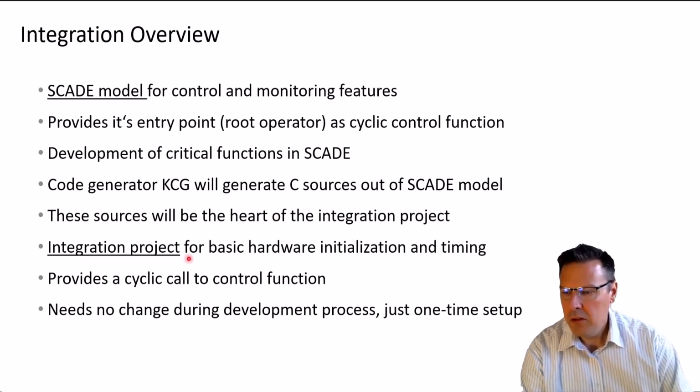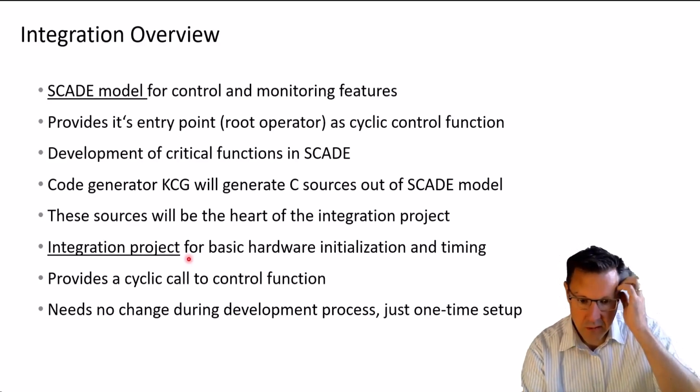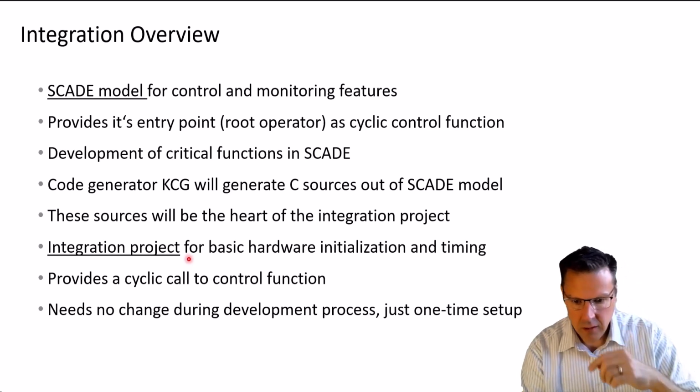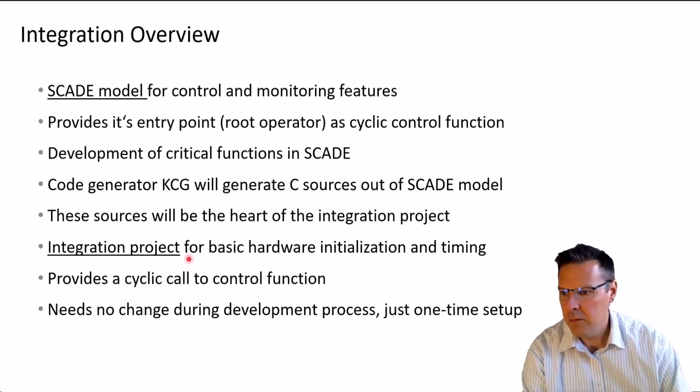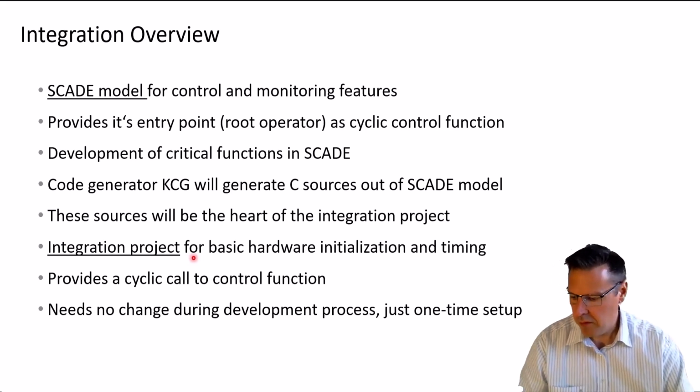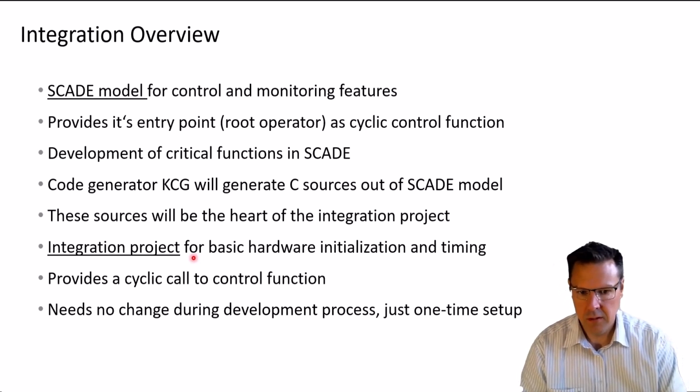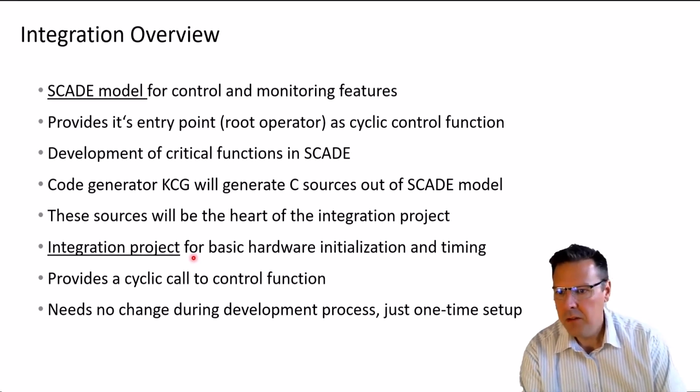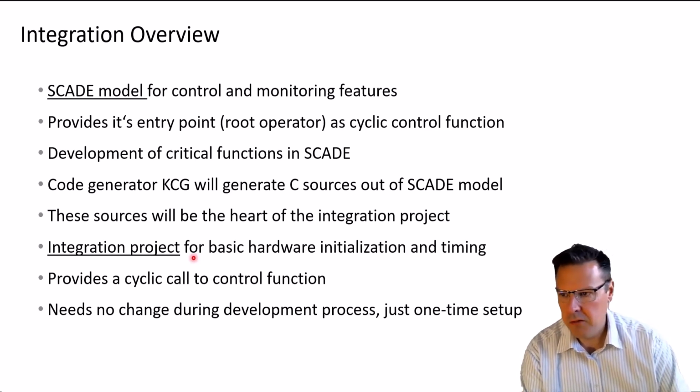Why do we need this integration project? SCADE is quite well abstracted from any hardware aspects. So for basic hardware initializations, hardware interrupt handling, basic port initializations, things like that, all the stuff which does a hardware abstraction layer needs to be outside of SCADE.